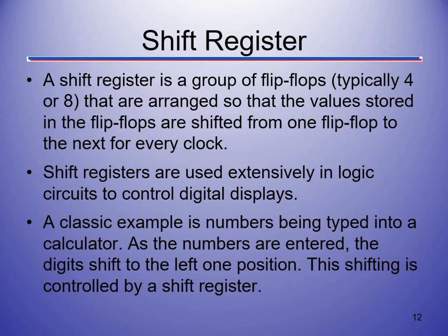All right, let's talk about a shift register. What a shift register is going to do is it's going to take our stored values in our flip-flop, and it's going to shift them through kind of an array of flip-flops. So if we have 3 or 4 flip-flops in a row, okay, it's going to shift the signal down each time. So every time, if it's going to shift through like 0, 0, 0, then it'll shift through like 0, 0, 1, so on and so forth. And that value kind of cascades down through the D flip-flops. Okay, so when do we use these?